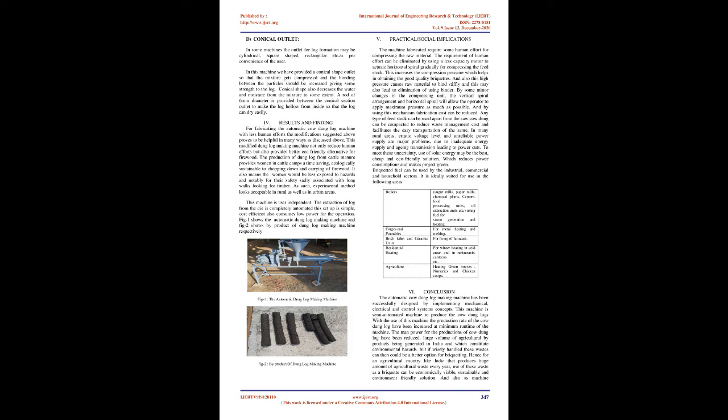The blade and the spiral rotate at the same speed. The purpose of the spiral is to push the mixture into the horizontal cylinder. The vertical spiral also compresses the mixture so that the mixture particles get bonded properly, forming a mixture suitable for the log. An oiling chamber is provided on the vertical spiral cylinder for maintenance and oiling the spiral for proper working.